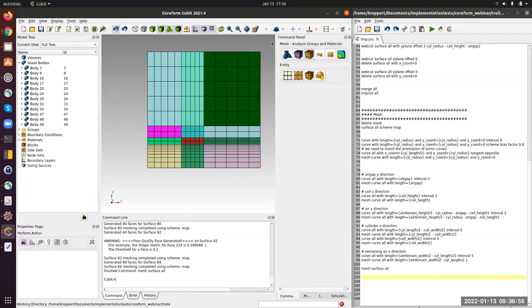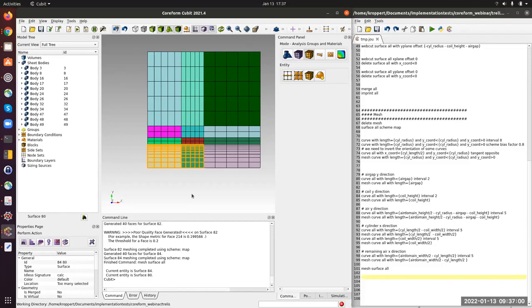So let's say this surface and this surface, we want to address these 2 surfaces in openCFS as one region, also the coil region and the air domain, because we need to assign materials and then later on also boundary conditions, for which behalf we use the node sets. Okay.